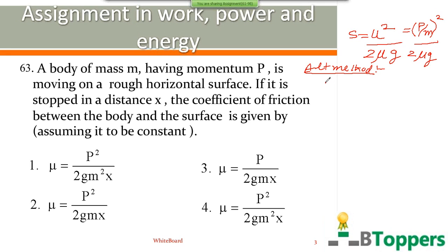by all the forces acting on the body. The body is moving on the horizontal surface. Let us consider the forces acting on the body. Its weight mg acts vertically downwards. Normal reaction force by the surface acts vertically upwards. Let small f denote the magnitude of friction force. It acts opposite to the direction of the motion.